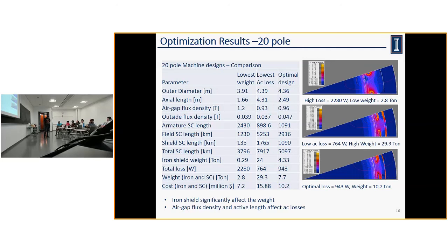Back up a step and explain what a shield coil is. So the shield coil is going to create an opposite field to contain the flux without it going outside the machine. That's the only reason we have the shield coil, and it's quite useful for electric propulsion design because people are around the machine, so we put a shield coil around the machine to contain the flux within it. Is that shield coil also superconducting? It's also superconducting.